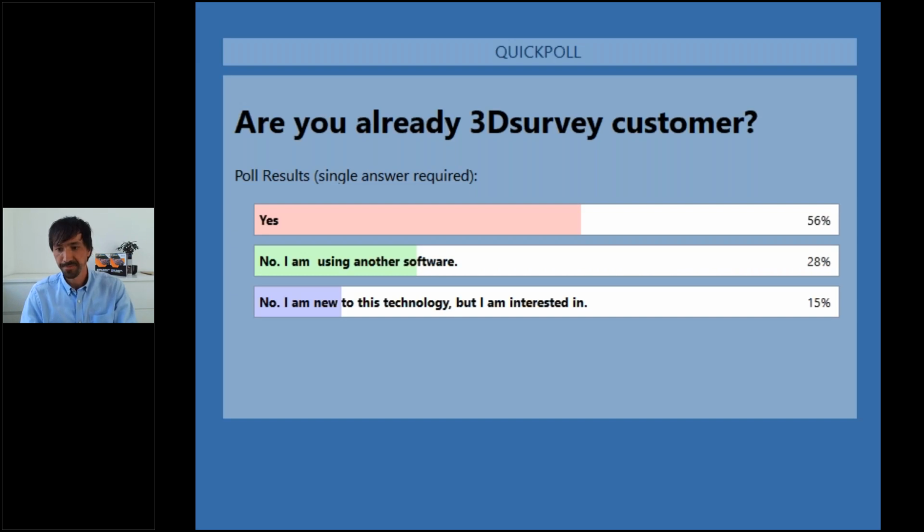In the meantime, let's start with our project description. In this webinar, I would like to show you how we did 3D mapping of an old building, which is part of a cultural heritage. It has a lot of small details which need to be documented before the restoration. The construction team asked us to deliver textured full 3D models with the highest possible detail, and an orthophoto of every facade in a resolution of 1 millimeter.